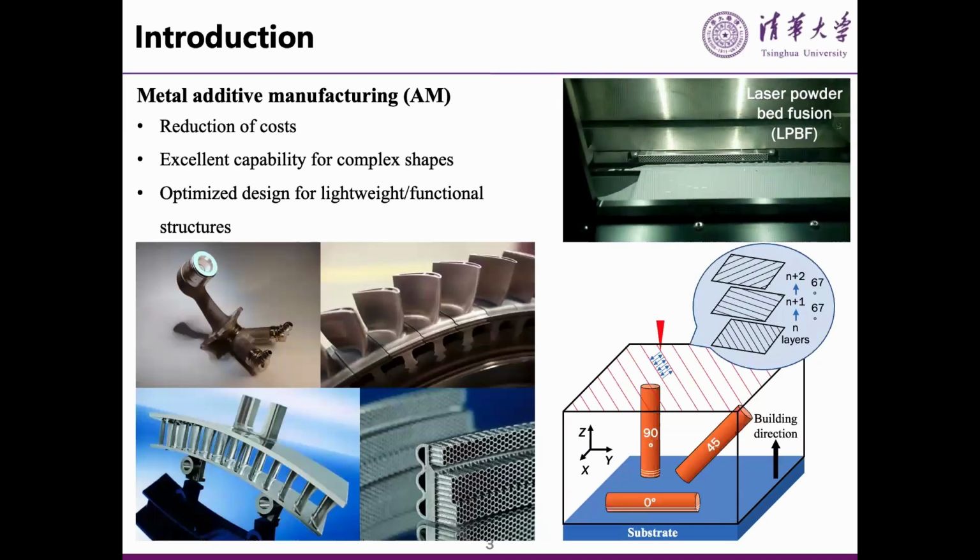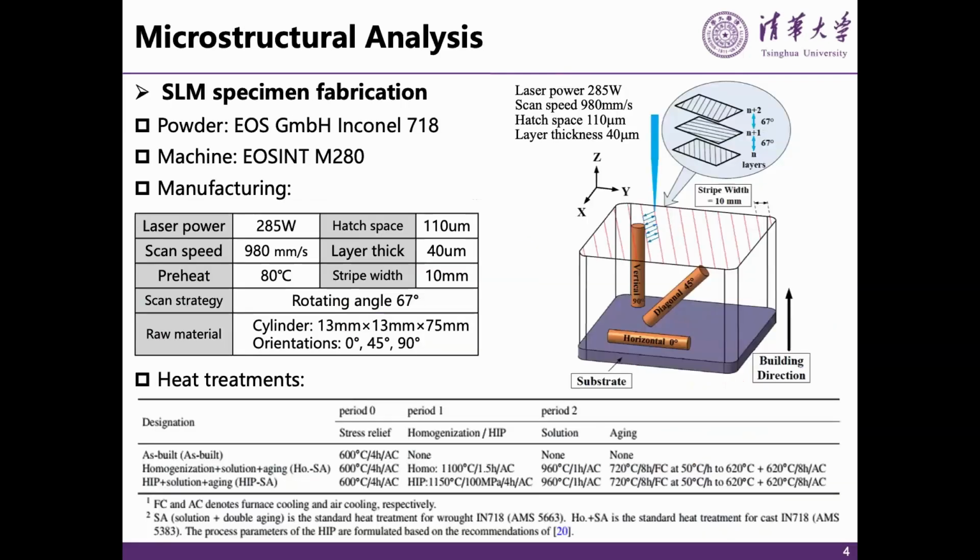In that case, okay, this picture shows you the application. It was said this kind of material will be used in engine design, but in reality the AM material parts are mainly static parts. The reason is we are not convinced to use them for rotating parts. Rotating parts are much more dangerous, much more important. If a rotating disk splits, bursts, the whole engine is destroyed, perhaps the whole airplane can be shut down. Therefore, it is very, very important in this case to know the material property.